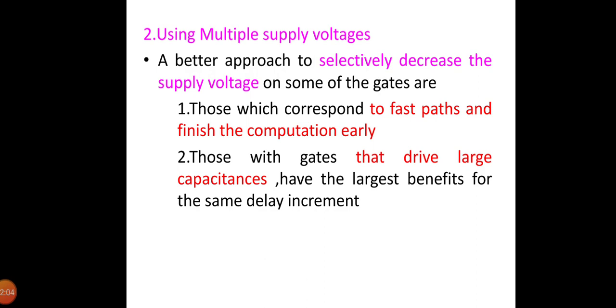The NMOS transistors operate at a reduced overdrive, and they have to be made large to be able to overpower the positive feedback. For a low value of VDDL, the delay can become very long. Due to the reduced overdrive, the circuit is also very sensitive to variations in the supply voltage.